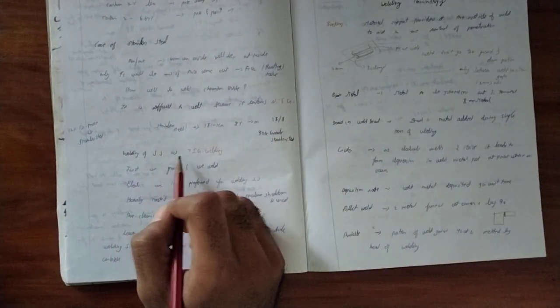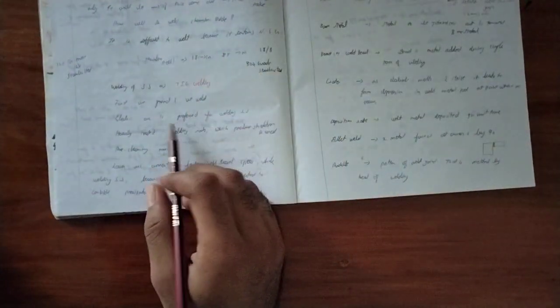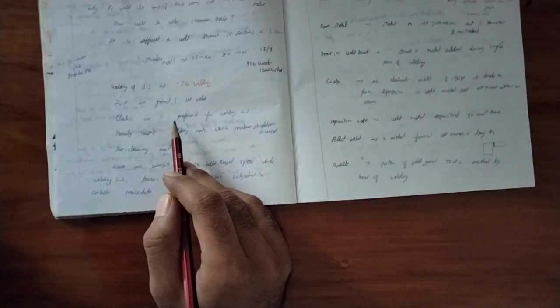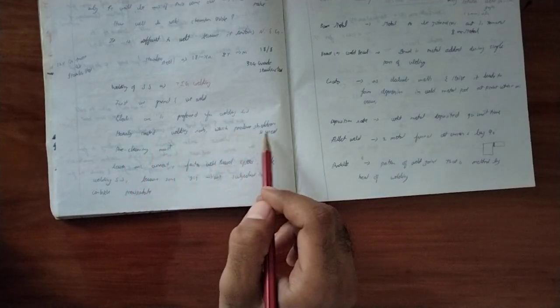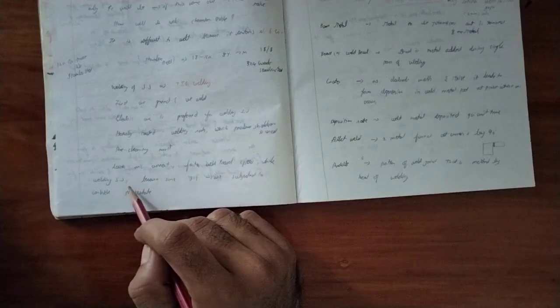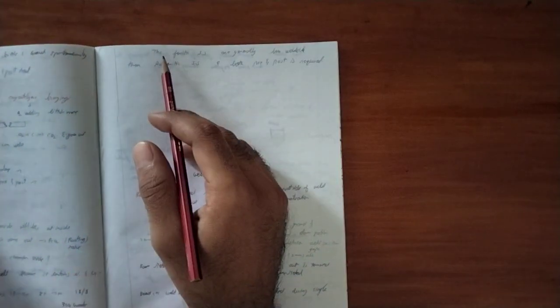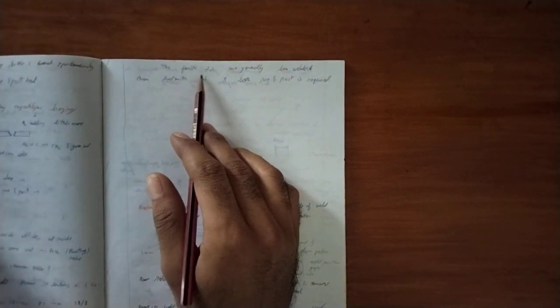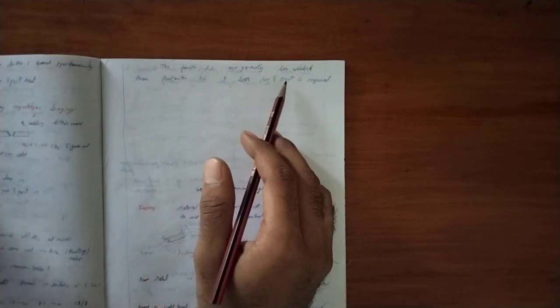So for welding of stainless steel we generally use tungsten and gas welding. First we grind them, then we weld them, and electric arc is preferred for welding of SS, and heavily coated welding rods. While providing the shielding, okay, pre-cleaning is a must, and lower the arc current, faster weld travel. While welding, some SS are subjected to carbide precipitation. Okay. So next one, ferritic stainless steels are generally less weldable than austenitic stainless steels because post heat and preheat are required.